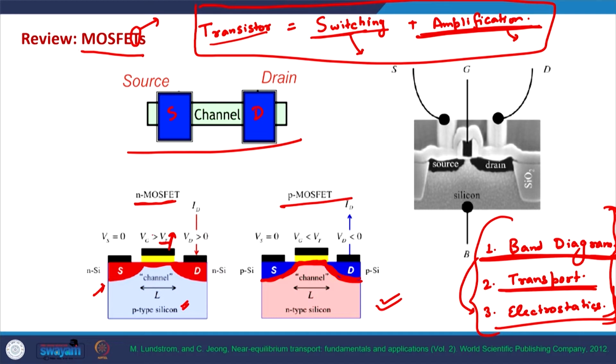When the gate voltage is larger than the threshold voltage, we will have a channel below the gate and this will switch on the device. So by changing the gate voltage, we can switch the device on or off. That's the basic switching operation of these devices, and it is achieved by changing the voltage or the electric field on the gate terminal, the third terminal.